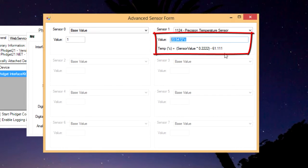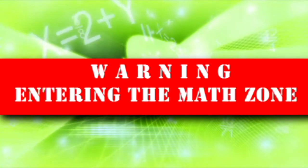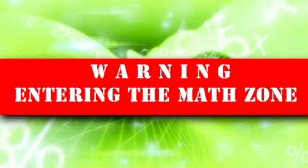Thanks to Phidgets, we know that the output of the probe times 0.2222 minus 61.111 equals the temperature in Celsius. We'll be able to use that same equation in SetInMotion. Now we need to know the mathematical relationship between Celsius and Fahrenheit, so we know what equations to use in SetInMotion. Here's how it all breaks down.